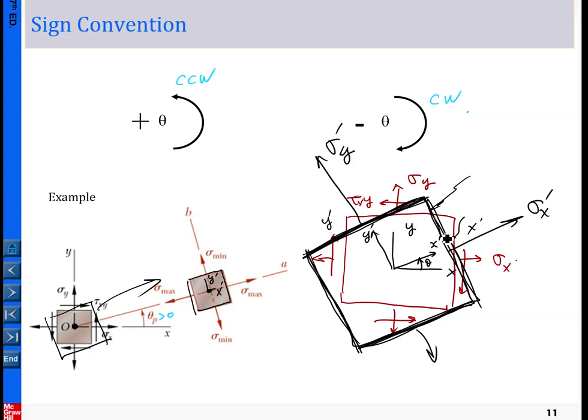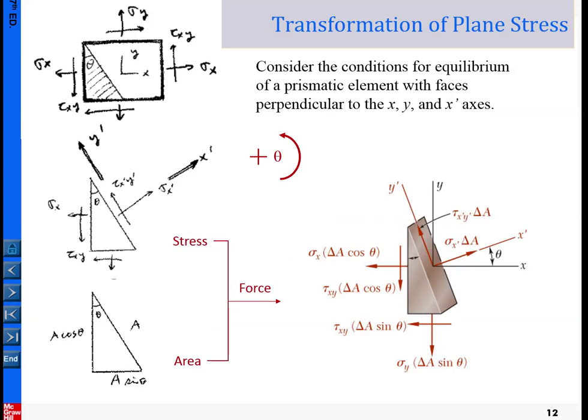For the transformation of the stress, we don't do rigid body translation. We only do the rotation of the coordinate system. However, to allow easy visualization, we simply offset the transformed element away from the original one. Again, that is to allow people to easily see the description. So keep this in mind.